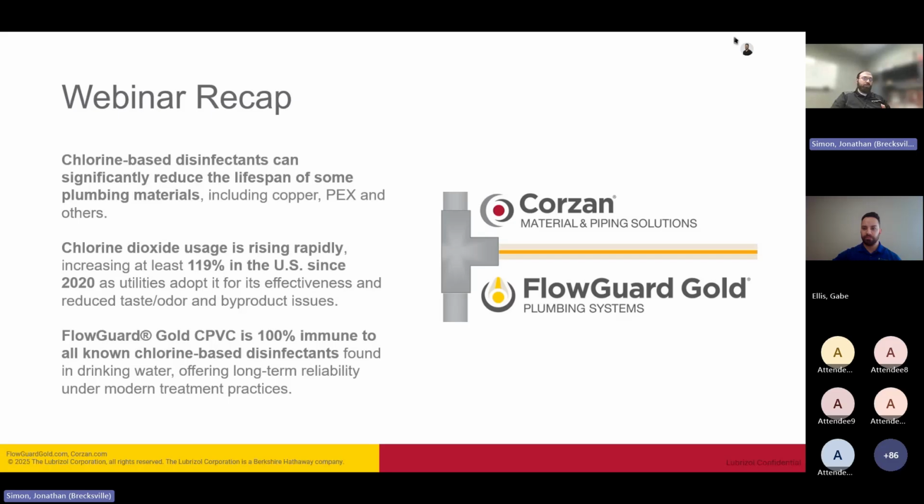One thing you can also find with a lot of these systems is they're loaded up with antioxidants that are designed to protect the pipe for a period of time against this oxidative degradation. But those antioxidants can also be consumed by exposure to things like UV light. So the short answer is it's the combination of temperature, pressure, ORP, and a variety of other exposures that may, over time, weaken or diminish the oxidative resistance of the piping.